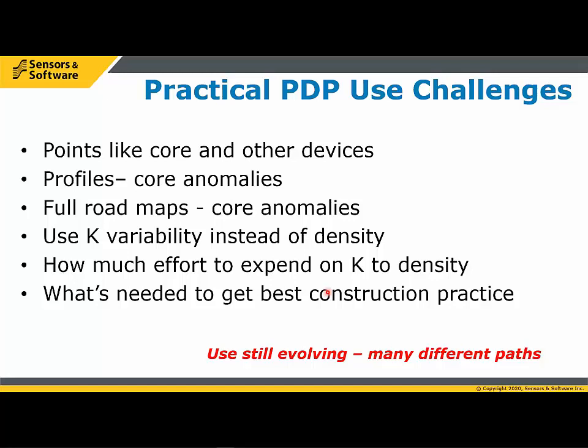Many of the people we talk to want to use their measurements to adjust the construction practice on the go, and that means getting fast turnaround of data. And what's critical is the uniformity and not the absolute numbers per se. On the other hand, you have certain jurisdictions dictating that the density has to meet a certain number, and there are pay incentives or penalties placed on using that absolute density number. So there's all sorts of interesting challenges out there for the community to deal with.